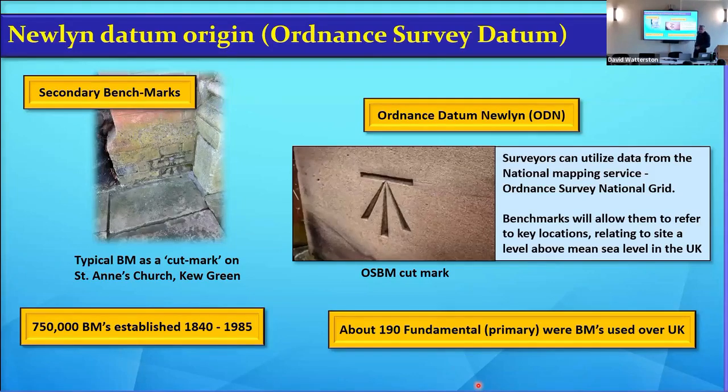Because if you damage it, it's going to be a huge knees up, all right? And there might be the odd time that you come across this. But again, from the deeds and all that, there should be something known as an easement. And an easement is a clearance on the ground that says you cannot build within 2 meters, 3 meters, 5 meters either side of this sewer run that's running round about. So you would know it was there. It would be written on the deeds.